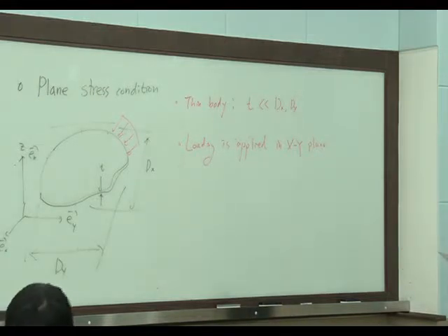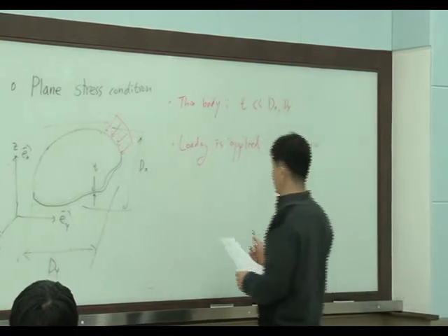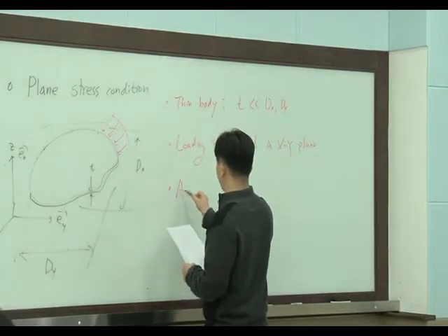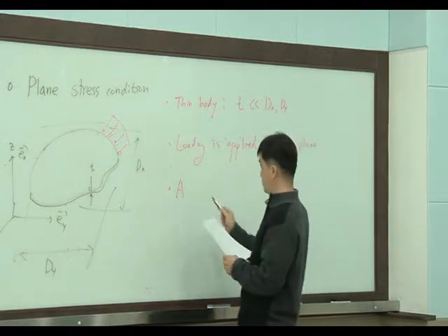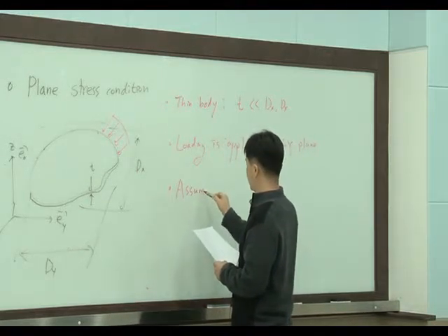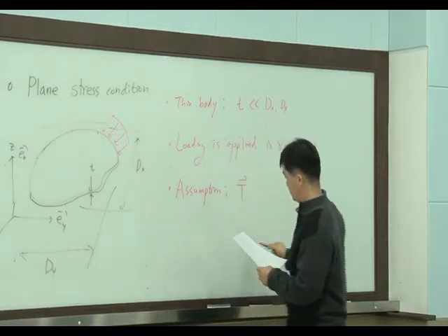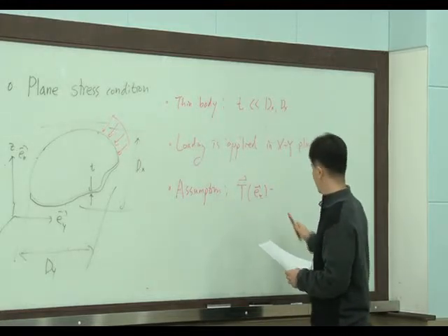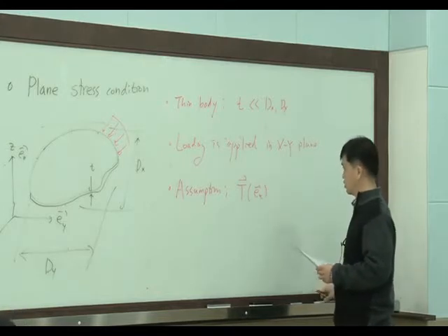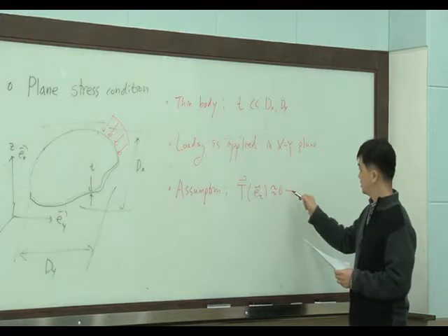If we have this kind of problem, we can use the plane stress condition. This plane stress condition is an assumption. The assumption is that traction in the z direction is very small, so 0.